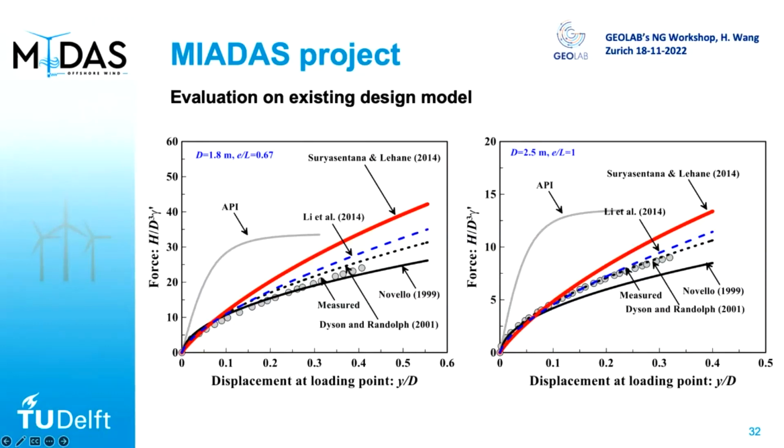Okay. I think this question can be answered by 2 points. First, the lateral soil reaction, basically these p-y curves themselves, actually change with the pile aspect ratio. If you check this design code, API, it was actually proposed for very small diameter cylinder piles, maybe 50 years ago. And now we have very large diameter, very short piles.